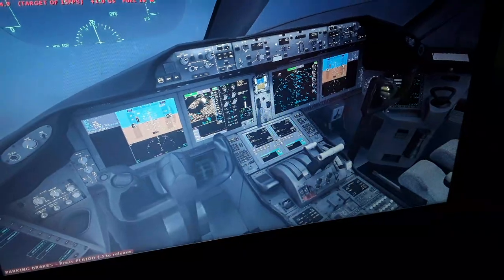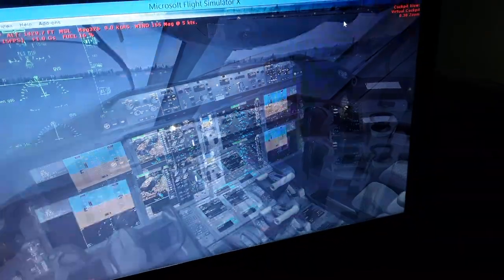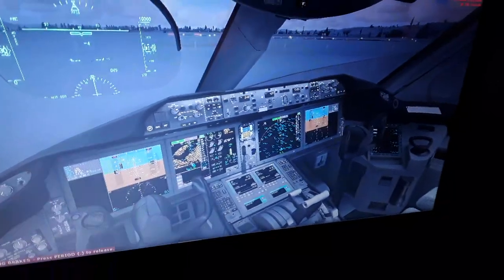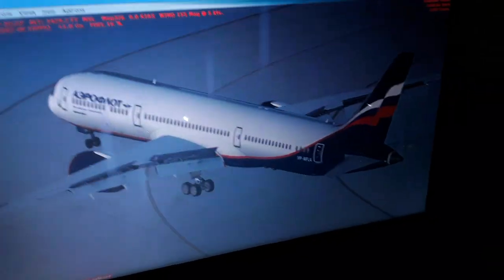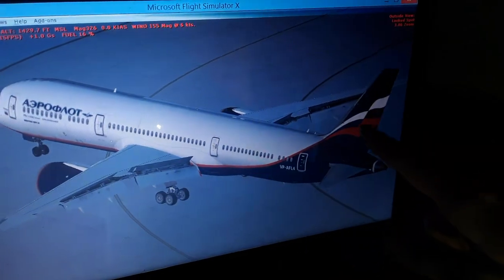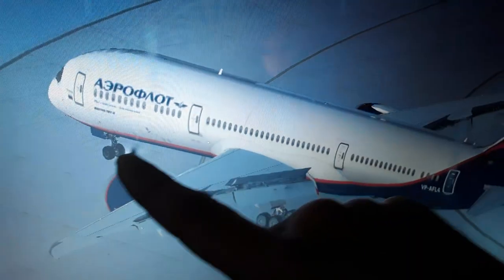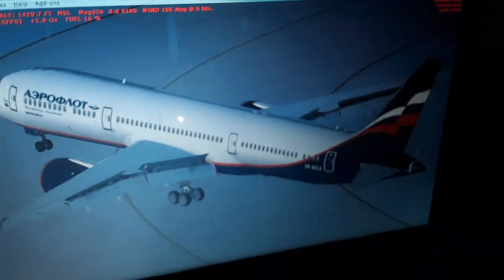When we move the rudder pedals, we don't need to move the tiller all the time. We just need to move the rudder pedals, also in takeoff and in landing. So from 0 knots up to 45 knots, or 72 kilometers an hour, the forward nozzle is deflected either left or right up to 76 degrees from the computer automatically.